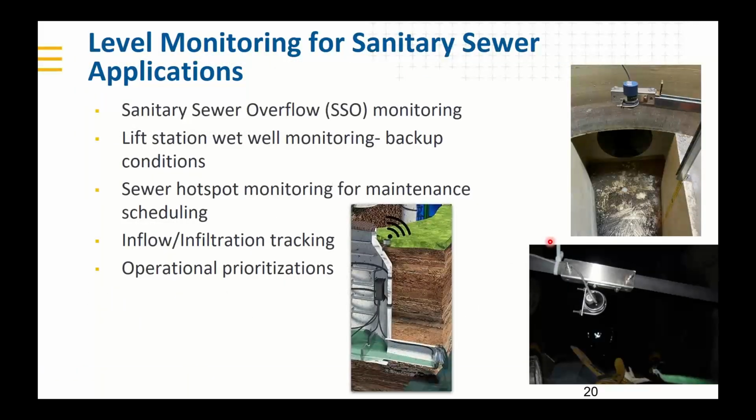So here's some different applications for our level monitoring. Obviously, we can help with SSO monitoring, alert you to when you're having some issues in your system. It can be used for lift station wet well monitoring as well. So you can see what sort of backups you're having, whether it be a pump failure or during wet weather.